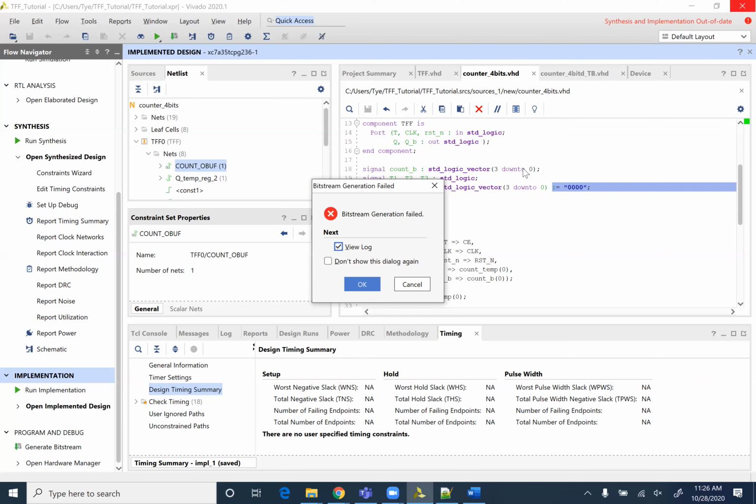Yeah. Because in high school we did something like that where we programmed it, and there was some complicated way of erasing it and programming it again. Yes. So the next evolutionary step after the anti-fuse technology was a technology that would be mostly permanent and was only erasable by UV light. So you'd open up the thing and shine some lights on it, and that would erase it. But now the newer technology is you have an FPGA that on boot up, the memory will program it. Yes. Like what you were saying.